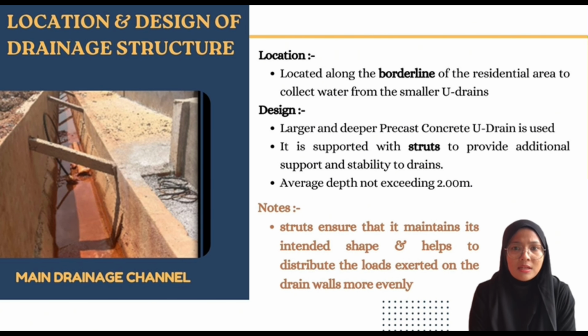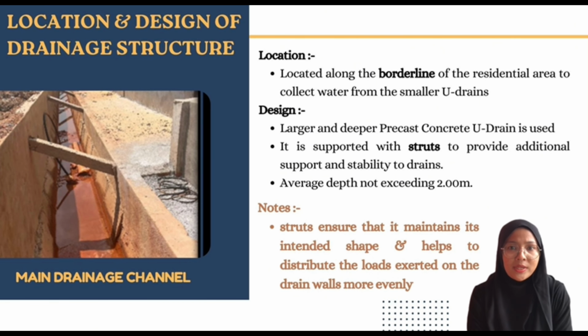For instance, struts help to prevent the walls of the drain from collapsing inward due to the pressure exerted by the surrounding soil. By reinforcing the drain structure, struts ensure that it maintains its intended shape and structural integrity over time. Struts also help to distribute the loads exerted on the drain walls more evenly, and this helps to ensure that the drain can withstand the weight of overlying soil, traffic loads or other external forces without experiencing excessive deformation or damage.